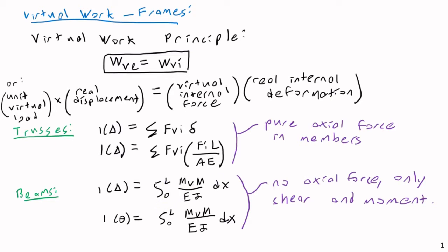Ultimately, what does this all come to? What unit would the right-hand side of the equations come to? It's going to be inches or feet? The actual final unit is going to be energy. This is the method of virtual work. So we have this internal work that comes from bending, and the right-hand side is the internal work caused by bending. What ultimately is causing that bending, whether it's a point load or a couple, doesn't actually matter to the expression for the internal energy.